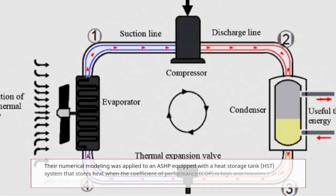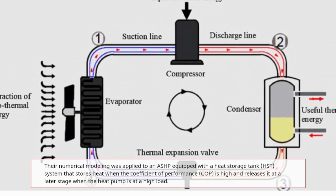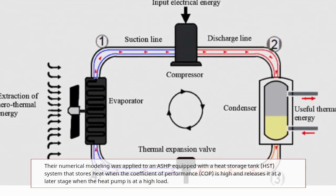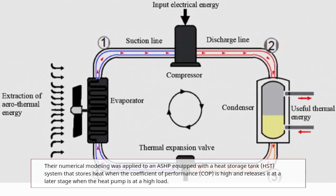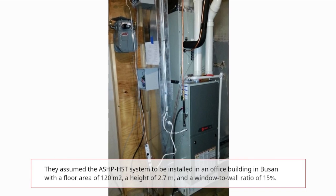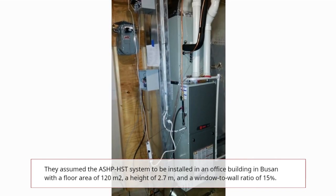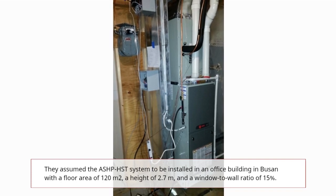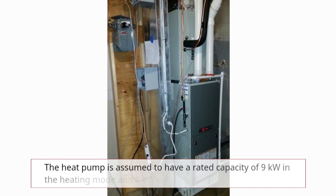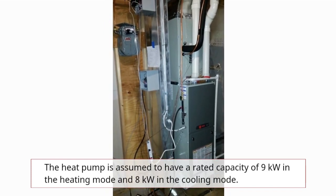Their numerical modeling was applied to an ASHP equipped with a heat storage tank, HST, system that stores heat when the coefficient of performance, COP, is high and releases it at a later stage when the heat pump is at a high load. They assumed the ASHP HST system to be installed in an office building in Busan with a floor area of 120 square meters, a height of 2.7 meters, and a window-to-wall ratio of 15%. The heat pump is assumed to have a rated capacity of 9 kilowatts in the heating mode and 8 kilowatts